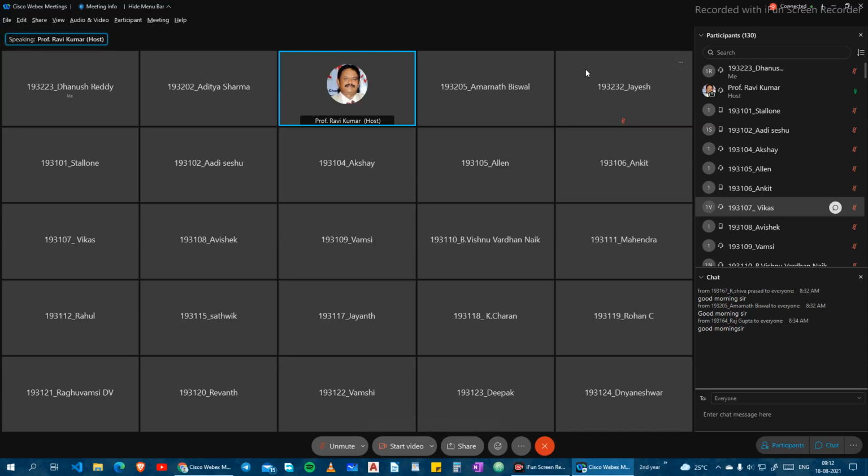Now the carburetor mode has gone, and the multi-point fueling system has come, because in the carburetor mode, every time the same quantity of fuel will be mixed and sent to the combustion chamber. But in a multi-point fueling system, whatever the speed you are going, whatever the power is required, it depends upon that. We have a micro power control based unit, and depending upon the demand of the power, the fuel is supplied. It will be reducing the scavenging process and scavenging losses also.